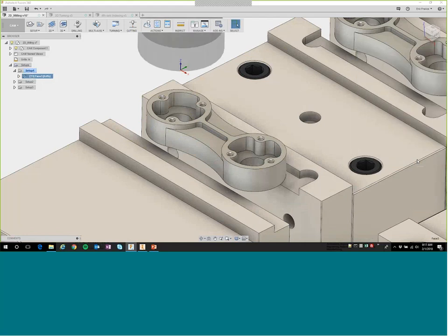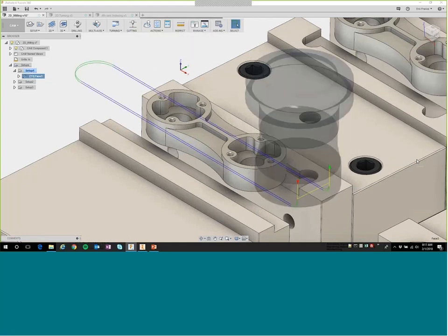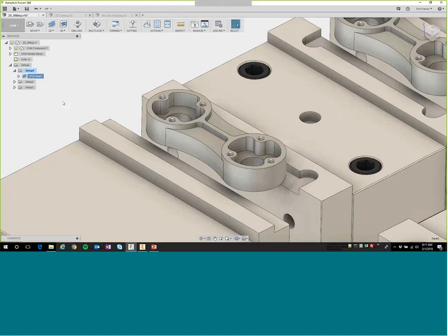Sounds good to me. And I go through and do that, and you can see that it's automatically updated the toolpath, the preview, where that path is going to go. Shows us it's definitely going to come off the part before it comes back around. It's going to do this in 2 passes. So I'm pretty happy with that as the operation that we want to have for facing this part off.